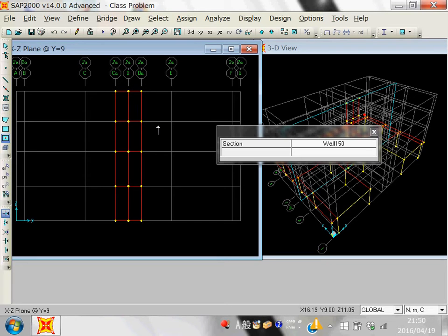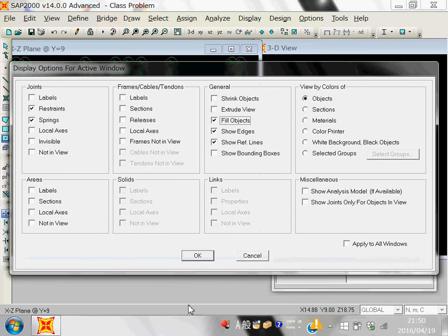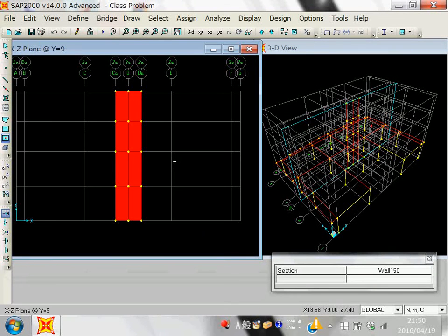Now if you want to add some door, you can do it, but for that you have to add an extra grid for the door. You understand? And similarly, now you can go to the elevation. If you click here and fill object, it will show you something like this. And now on which elevation do you have to go?